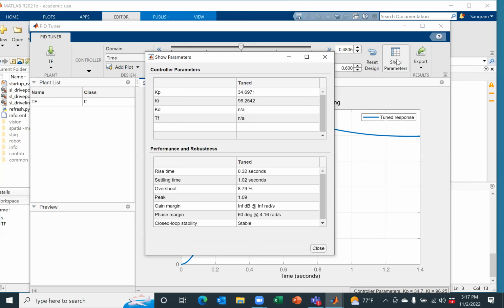Everyone understood this? Now, gain margin and phase margin, both of these concepts relate to how far the eigenvalues are from the imaginary axis. The classic definition of gain margin is the amount of gain that you can add into the system till the system becomes unstable.